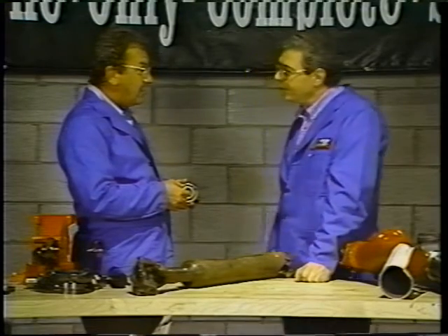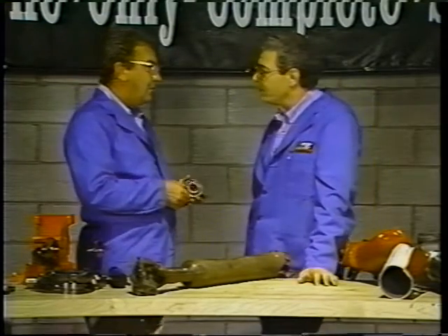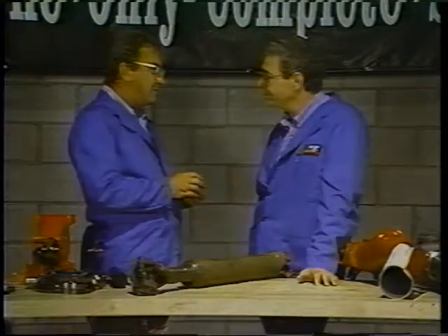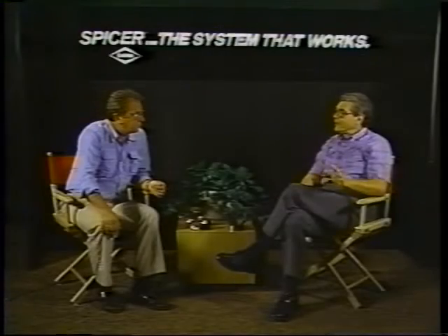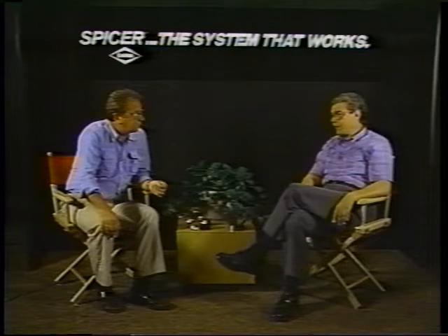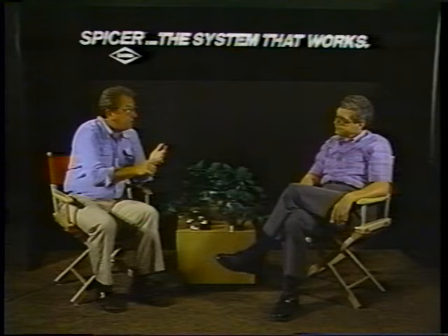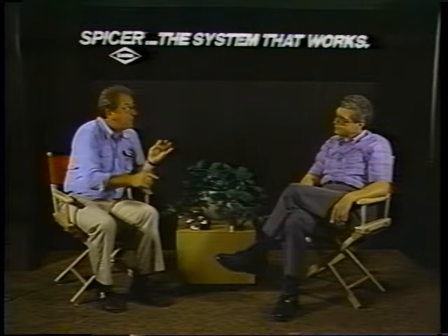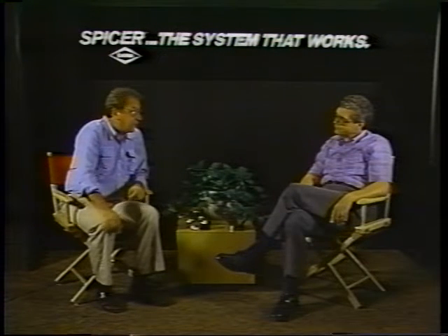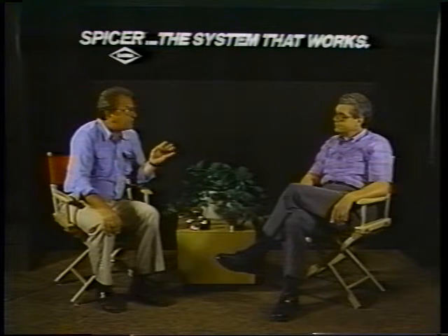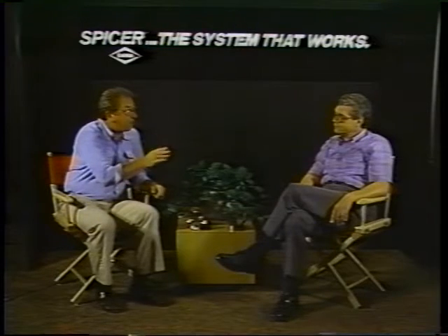Thanks, Tom. Now, let's go someplace a little more comfortable, and you can give us a recap of what we've just talked about today. Okay, Tom, let's go over the main points you made, starting with U-joints. Well, U-joints, trunnion diameters, ends and bearing cups are the main areas to check for wear. Now this may show up as brinelling, spalling, or end galling.